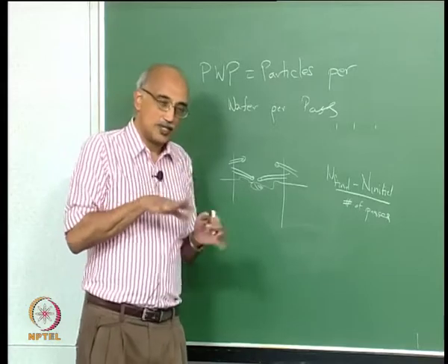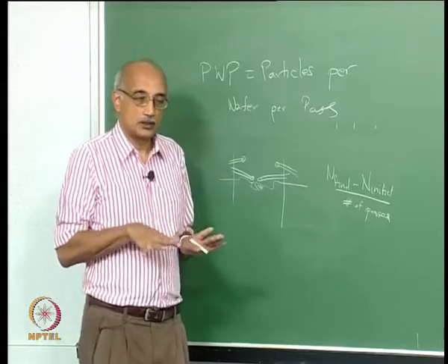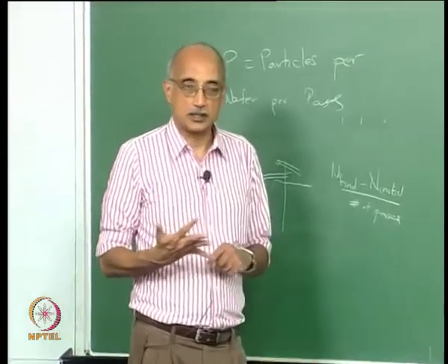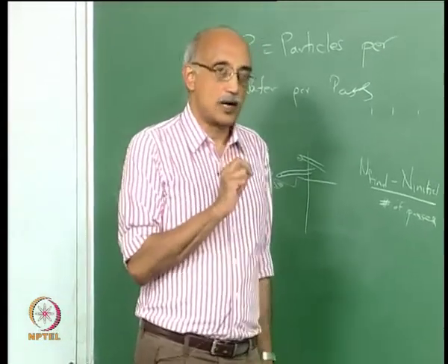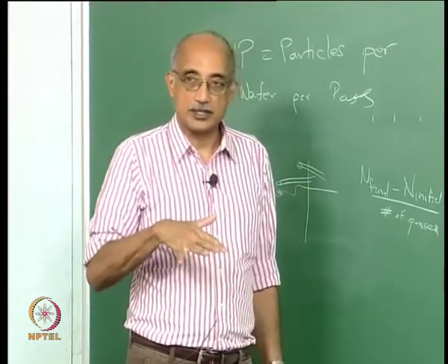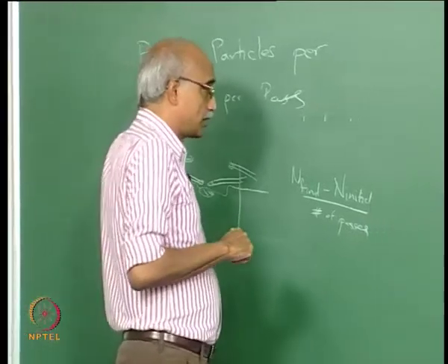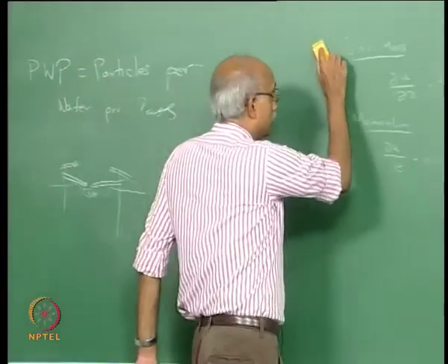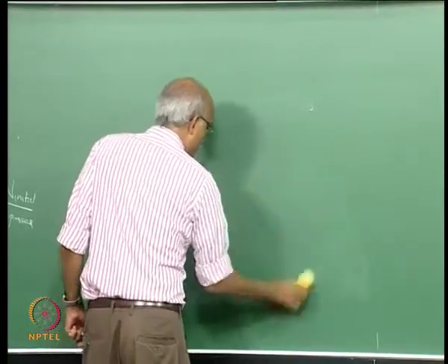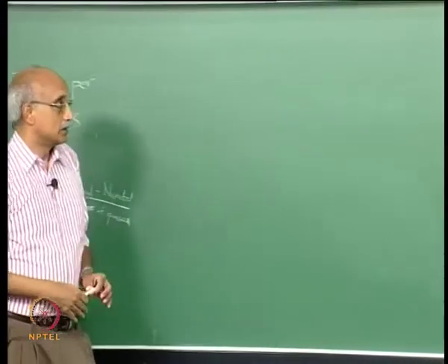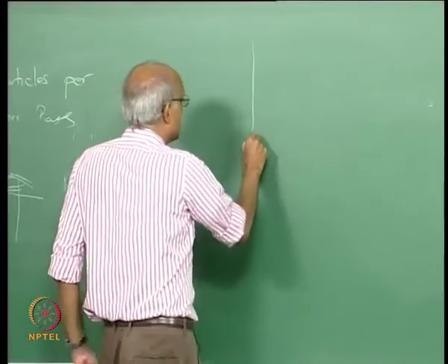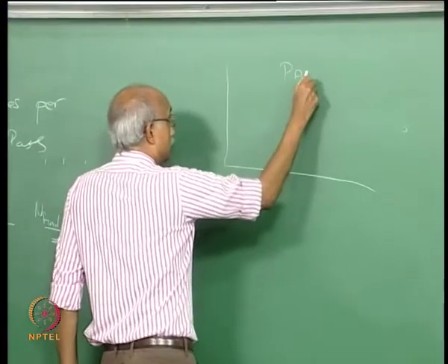So this differentiation of sources is very important, because it allows us to do a Pareto type of analysis to identify the top contributors of particles in a clean room and then take steps to minimize them. The Pareto methodology is one that essentially enables us to rank sources of particles inside a process. So the way that works is, in a Pareto chart,